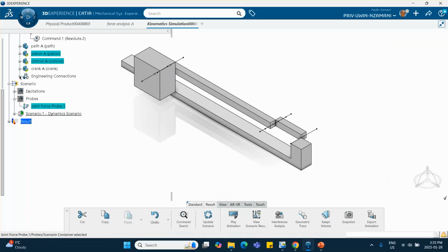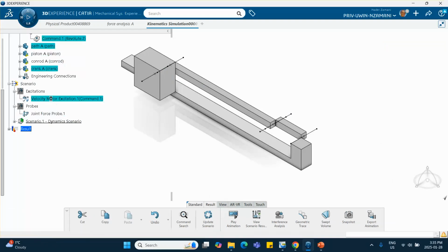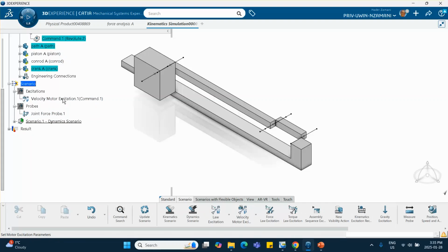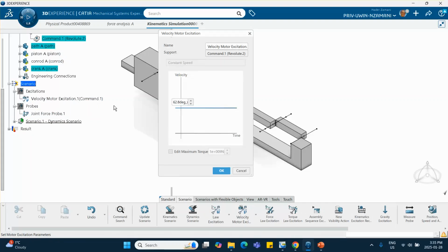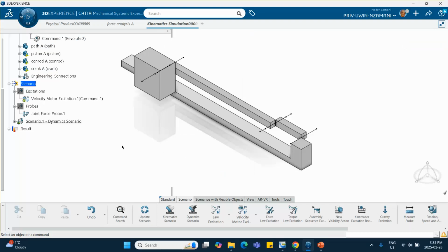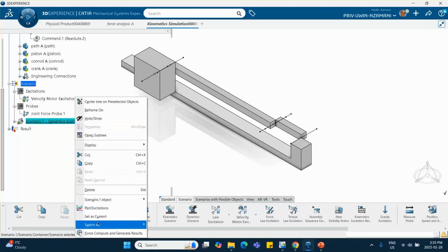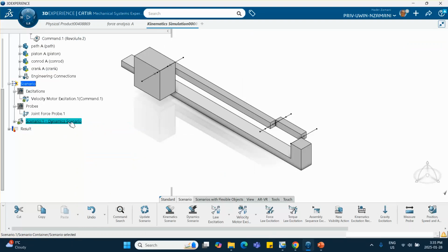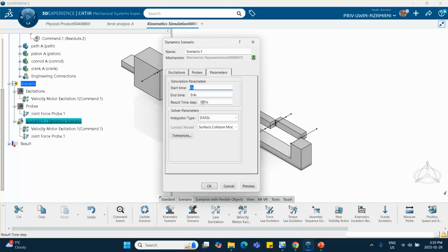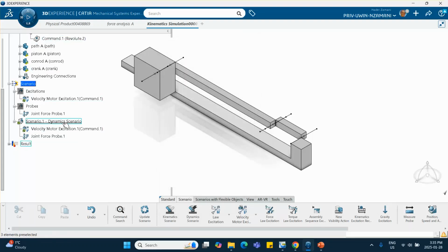First of all, my velocity excitation, I want to double check, make sure it's okay. Oh, rad per second. Not degree. Rad per second. Say okay. All right, now I'm going to run it. I'm going to put that thing back on 0.001. Say okay. Now run it.